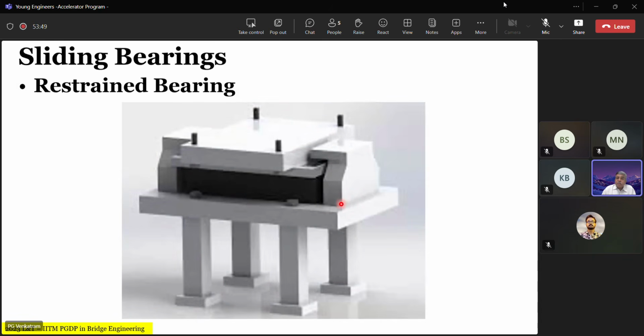Why? Because the bottom plate abuts against the top plate at this location, preventing translation in this direction. So you can engineer solutions with elastomeric bearing which mimic unidirectional movement, bidirectional movement, omnidirectional movement. All that is possible. It's only a matter of how you detail the bearing top and bottom plate. That's all.